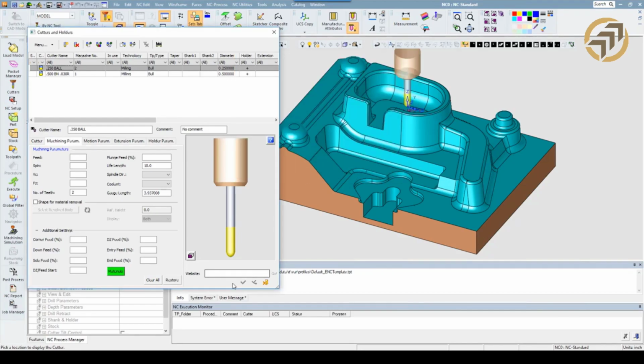but that's really big, because if you're cutting something and you load in the wrong material, or you have the wrong down step because you think that you're cutting a different material, or if you're just cutting something and you're in a rush and you have to go back to change the speeds and feeds, you can just update your material in your NC setup and update your tools, and you know the speeds and feeds are correct, and you don't have to manually type in those numbers.